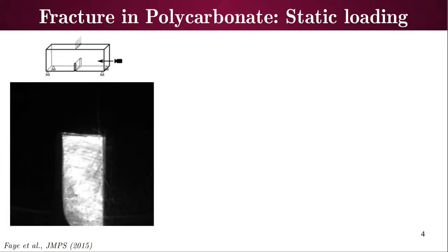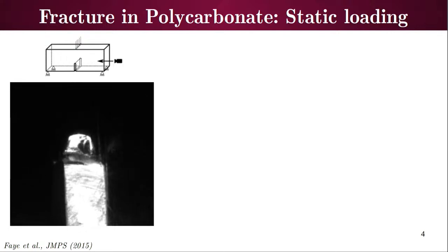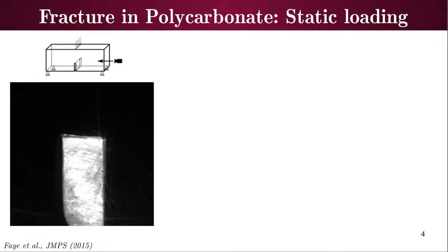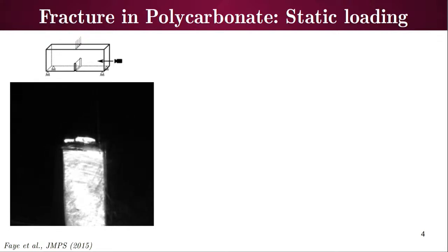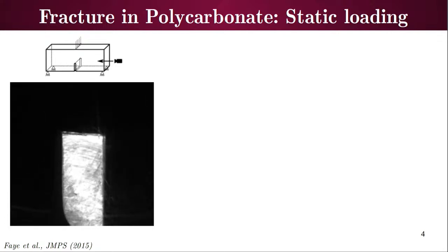When the loading starts, somewhere ahead of the crack, defects start appearing. The specimen does not immediately fail. There is an accumulation of defects ahead of the crack, and once sufficient damage has accumulated, it joins with the main crack and the fracture happens.